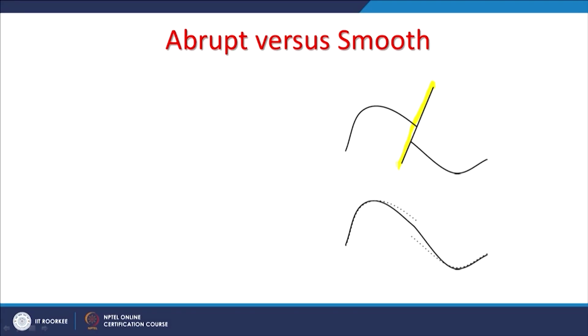Or there may be a geological dike, a quartz reef, or a geological fault, and therefore abrupt changes will occur in my surface instead of a smooth surface, because natural phenomena are not always represented in a smooth fashion; there might be abrupt changes. So, abrupt interpolators allow for barriers which we can use in interpolations, whereas smooth interpolators produce a smooth surface.